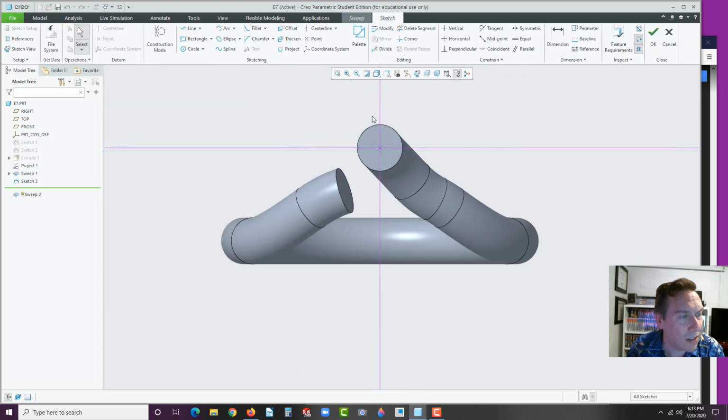What I would recommend now is, I've tried this and I don't want to try it right now, but in some releases, maybe all of them, if you use the project tool, you'll have some issues, okay? It could be fixed, but it's a little tricky. The easiest thing I've found is just go to Circle and click on the center point and snap it to the outer edge of that circle, and then middle click twice. That way it's locked in and it will actually follow the same diameter of the wire all the way through